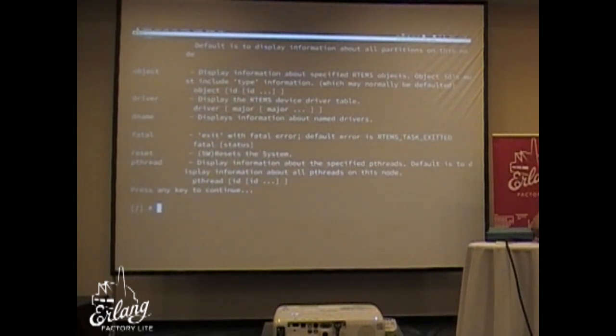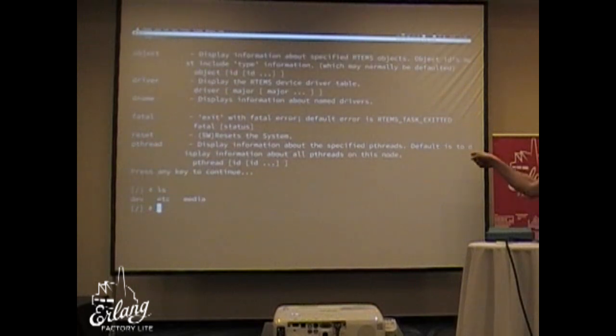And this particular build, this image that we booted now, has SD card support. So you can see this media folder here in the root partition. If I would show you the other demo with the RGB LED, you would just see dev and etc because it doesn't have any SD card driver. It still boots from the SD card because the bootloader supports loading it, but the application itself, which contains this shell, cannot do it because there is no driver.